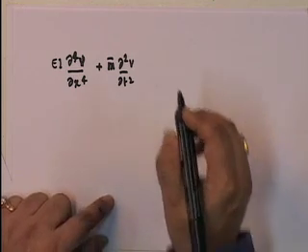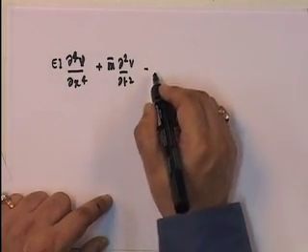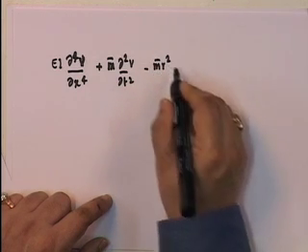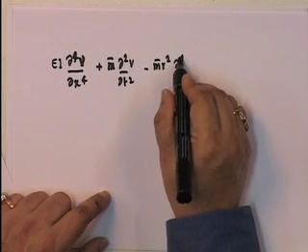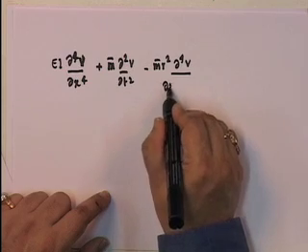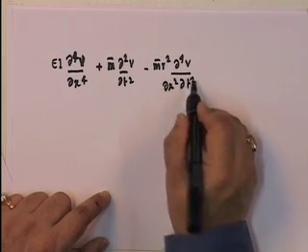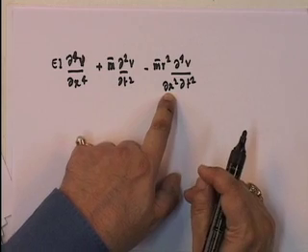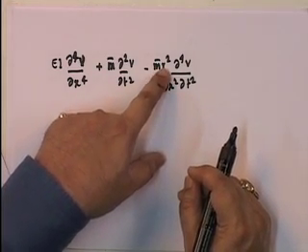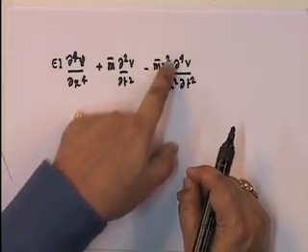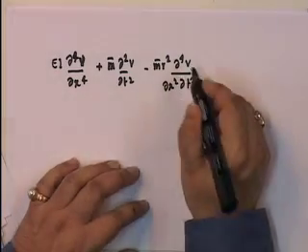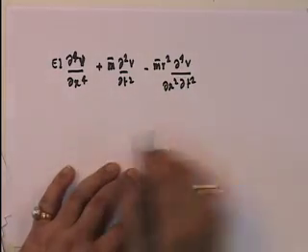Now, in addition, you have m bar r squared del fourth v upon del x squared del t squared. Now this is a combination of what? Because this is m bar into r squared, there is a square of distance. This part takes care of that distance. So, this is the rotatory inertia purely.